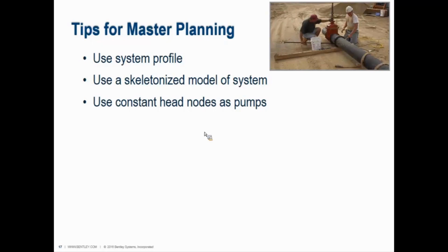You can also get away with using constant head nodes as pumps instead of actually putting in pump curves. The constant head node means it's going to be delivering a certain amount of head regardless of the flow. And you can even run extended period simulations at that point.